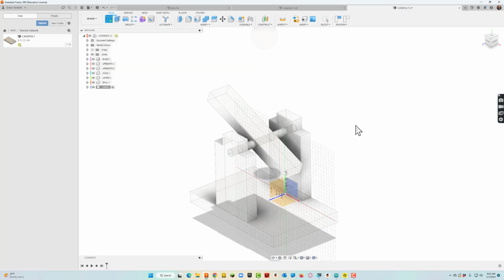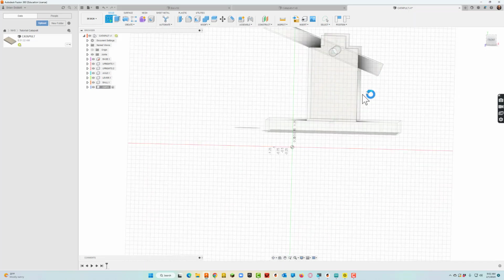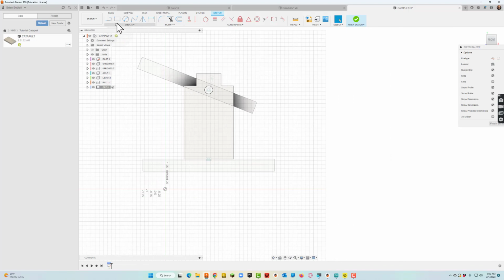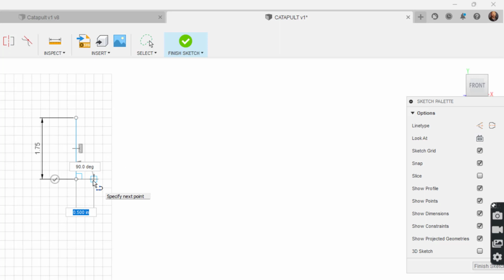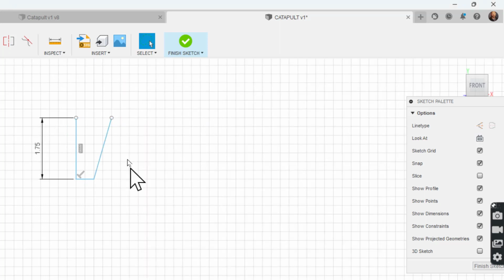There's several ways to make a cup. I'm just going to keep mine simple here and do another revolve. So I'm going to use a line this time. Our cup, let's say it measures like 1 3/4 inches tall. And the base of it is a 1-inch circle, so it's going to be a 0.5 radius there. Then I'm just going to come up. I just drew an angled line because I knew it does something like that. But I'm going to draw a line that connects these two now. And the radius at the top, make that a 1-inch radius.